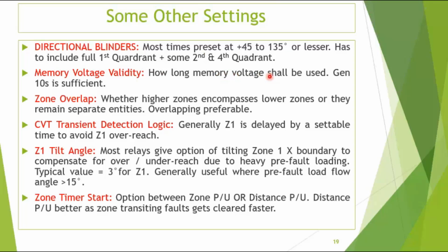Memory voltage is used to check whether the fault is in forward or reverse, and generally some validity setting, the time validity, how long memory voltage will remain active. That is what this setting means. Generally 10 seconds or whatever the relay default is given is sufficient.